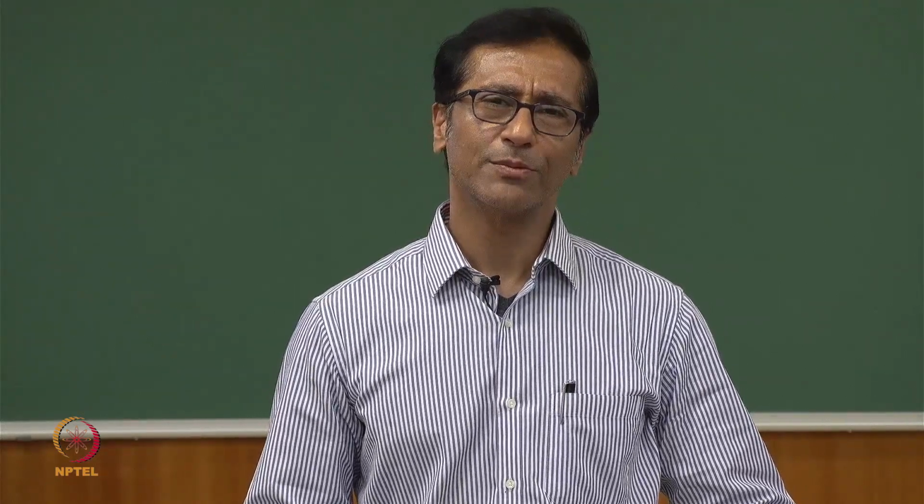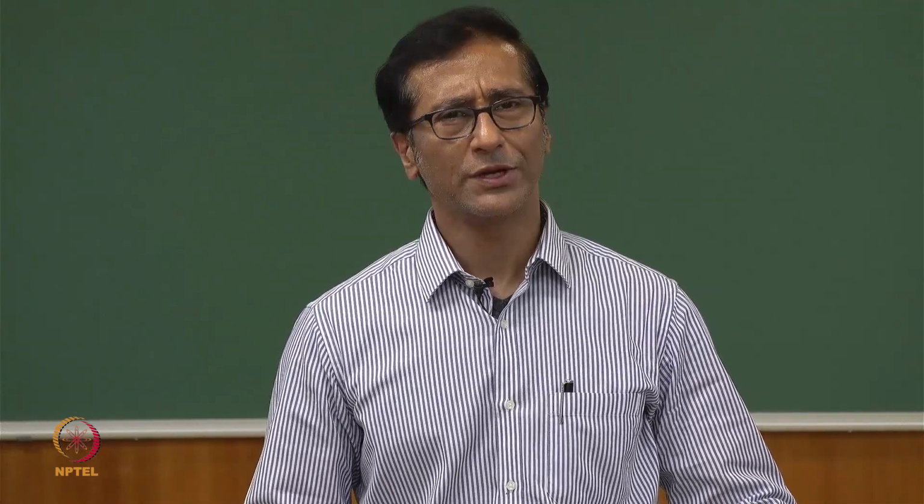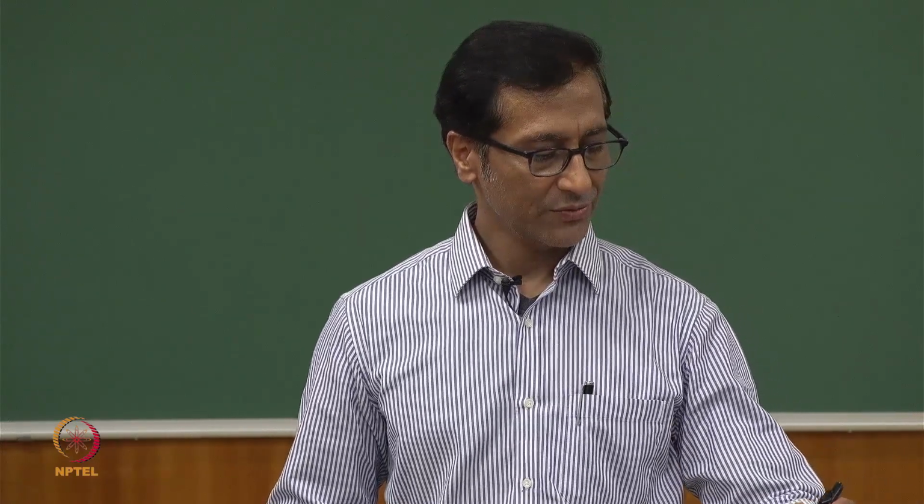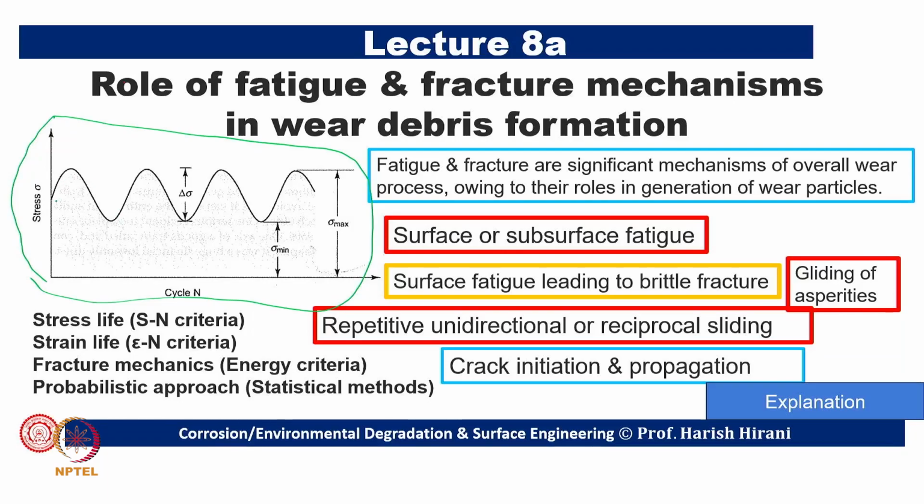Now, when I think about fatigue, what comes to mind? Something like reversible loading, reversible stress, and that is why it has been shown here. We show stress, and then the reversal. There is a maximum, then a minimum, then a maximum, then a minimum, and the stress magnitude varies by delta sigma. We have a maximum value of stress and a minimum value of stress. This minimum value, sigma minimum, can be 0, or it can be the negative of the maximum. So there are tensile and compressive stresses, which comes naturally when we think about fatigue.